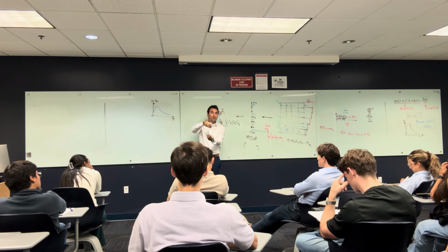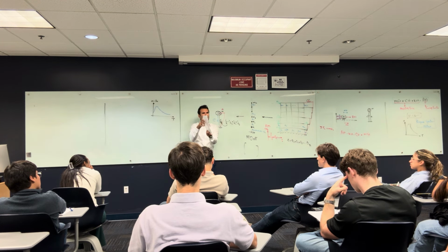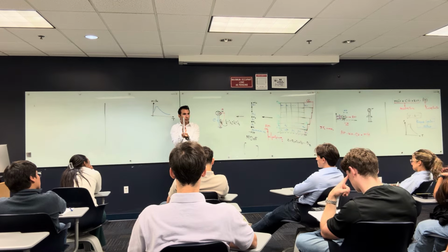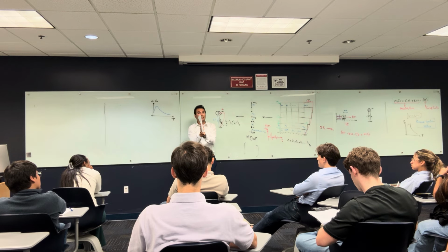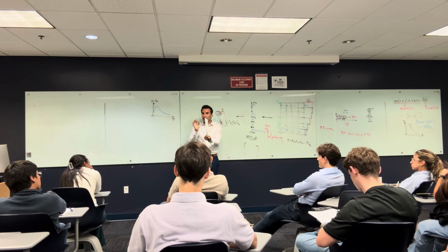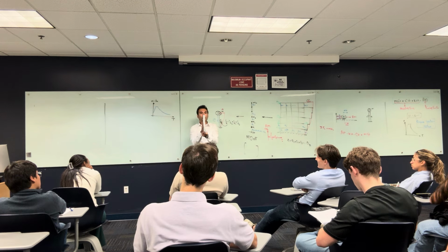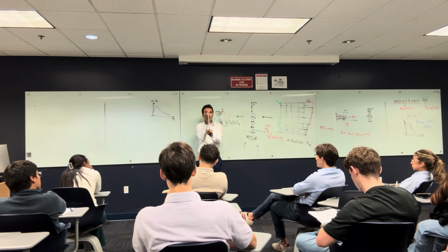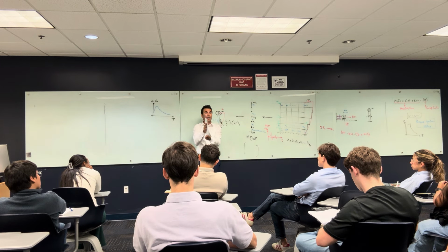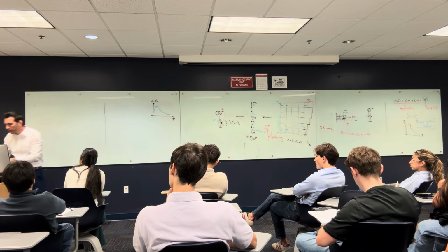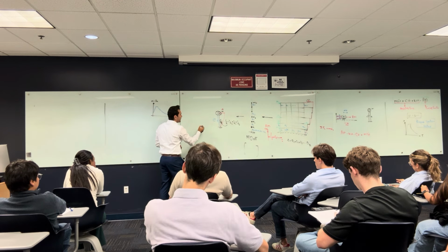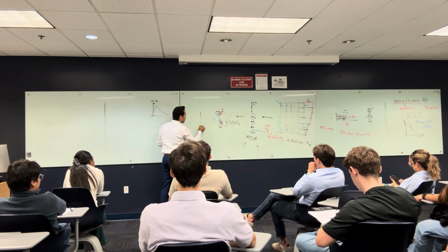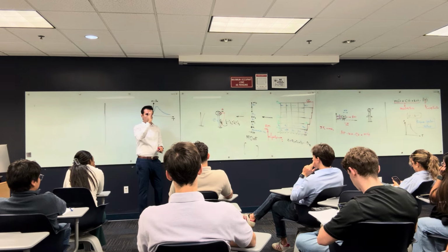And sometimes the structure can move with two nodes, like something like this. You're gonna tell me, but I never saw a structure doing this before. Right? I can imagine that, even if you never saw the structure making this. These displacements happen, but they are very, very small, so you can't recognize them. But the thing is, the main displacement is the one that moves like this. This one, moving like this, is very minimal, but it happens. That's what we call the mode shapes of the structures. If your structure is a single degree of freedom like this, it only has one mode shape. What is this mode shape? It is this. It either moves like this or moves like that.